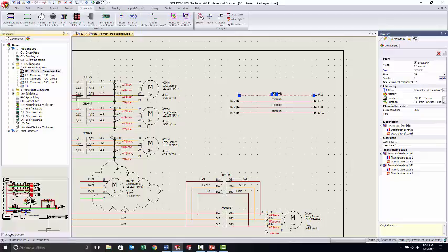Will it organize all the to from text, so I don't have to go put it all in numeric order? What do you mean? The to from text. We'll have a power supply on page 10. Yep. And then on page 11, 12, 13, 14, you've got all different devices on those pages. And when you do the to from arrows, the reference numbers never drop in order, and I've always got to take 5 minutes and manually sort them all out so they're in order. This is going to do them in consecutive order, so it's always going to do one arrow in, one arrow out.